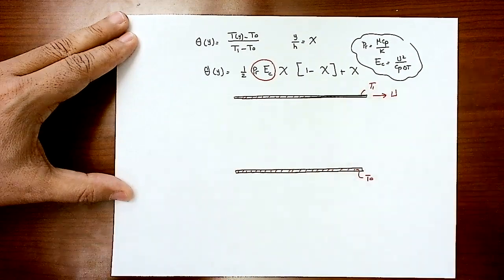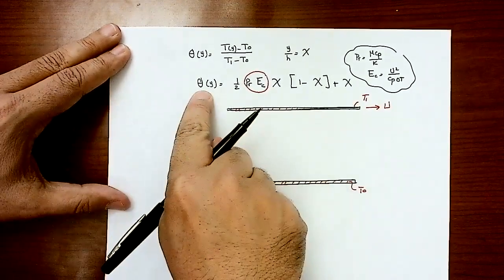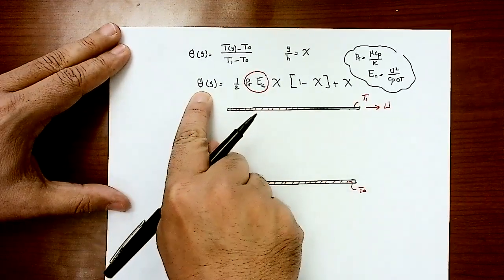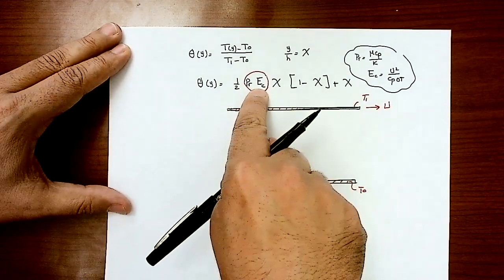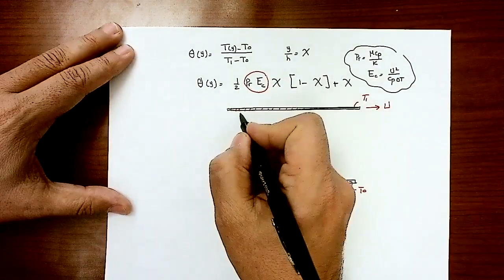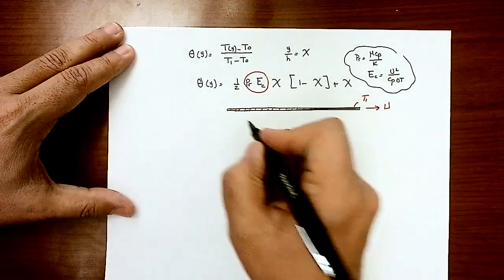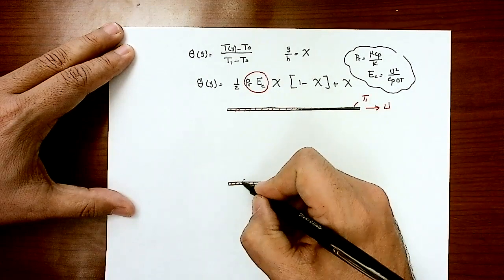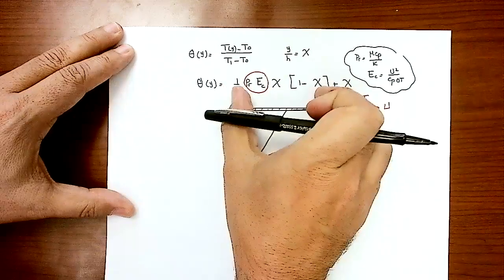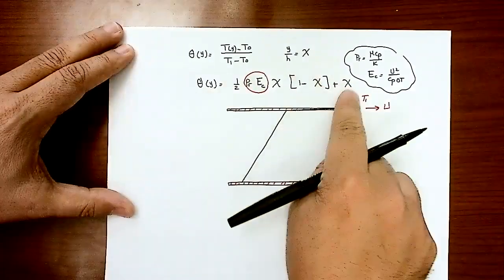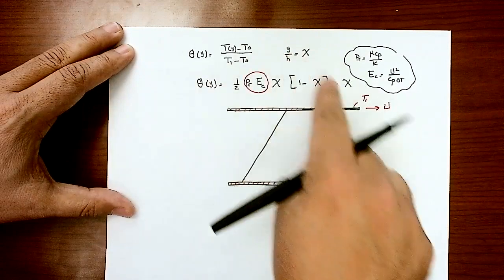U capital is the velocity here. So theta, the dimensionless temperature ratio, is mainly a function of Prandtl times Eckert number. For example, if Prandtl Eckert equals 0, the whole term goes away, and you end up having theta equal to y over h. So it's going to be a linear distribution, right?